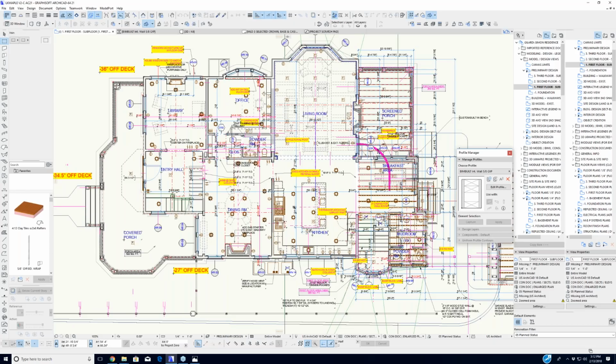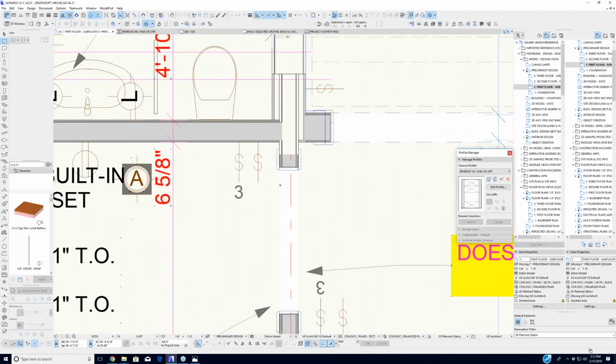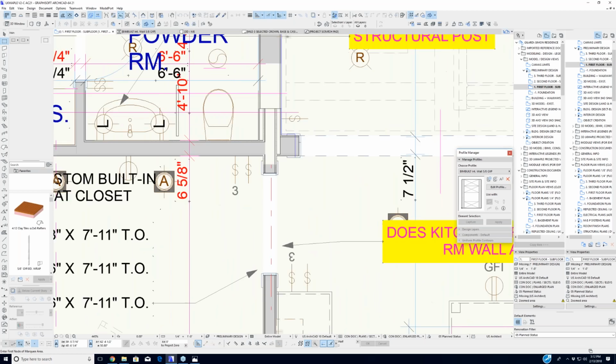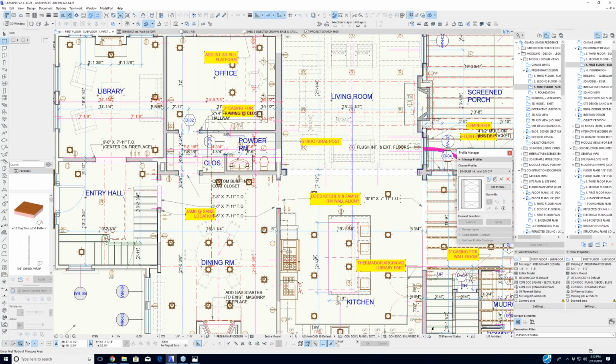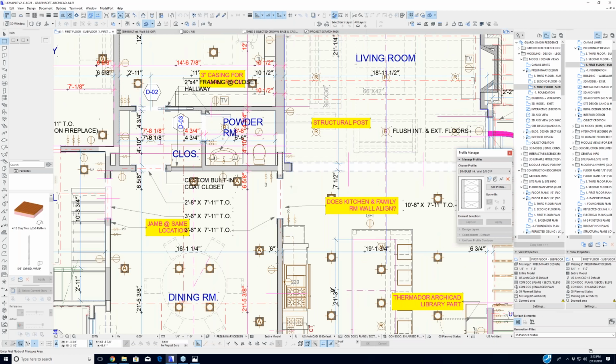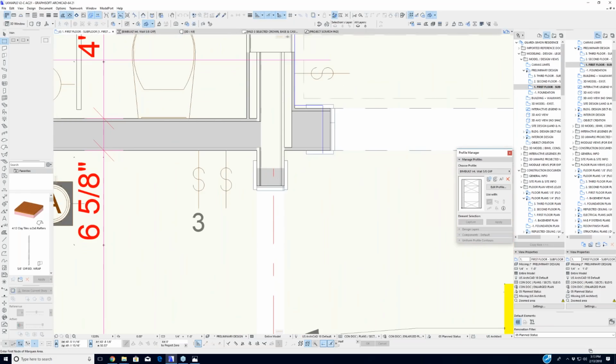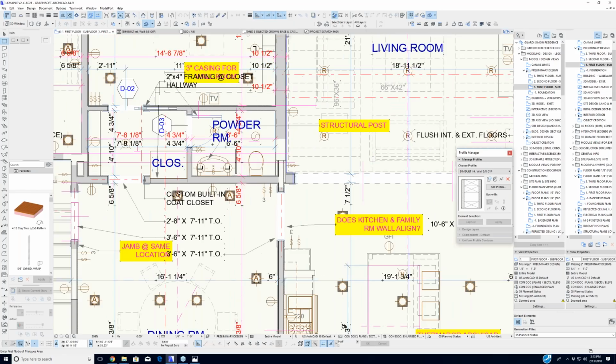And the most important thing is to document jambs. And when I say that, I'm going to zoom in here. What I mean is the actual wall. When you walk through an opening, what is that true dimension? Even though these walls might have been 2 by 4, in 1871, that's an actual size, so it's a full 4-inch, and they're doing plaster and lath. The plaster and lath has a dimension. It's going to be much more than 1/2-inch drywall. And the only way to know what that core really looks like is by measuring the jamb. So every single jamb is measured and modeled that way.